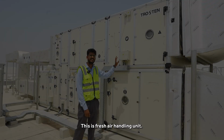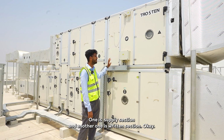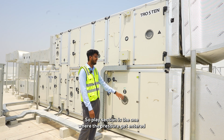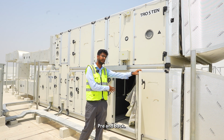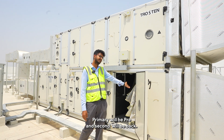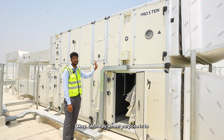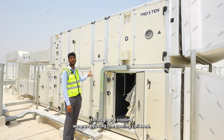This is the fresh air handling unit. As you can see, it has 2 sections. One is the supply section and another one is the return section. The supply section is the one where the fresh air enters, and similar to the AHU, it has 2-stage filters, pre and back. Primary will be pre and secondary will be back. Then you have the enthalpy wheel. The enthalpy wheel's purpose is to pre-cool the air. Through pre-cooling, we are reducing the cooling coil load.